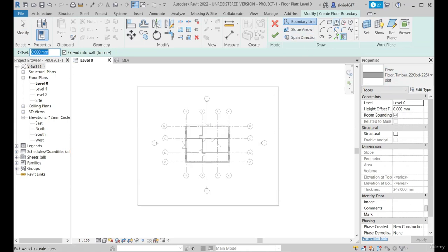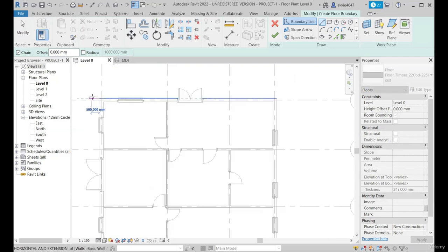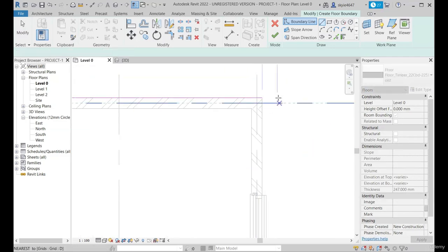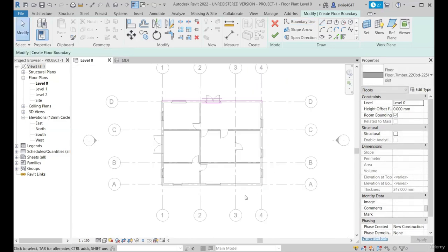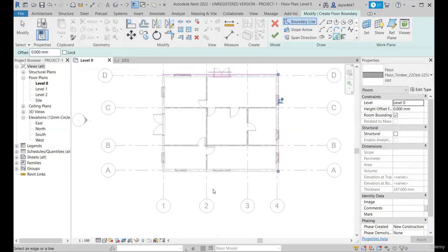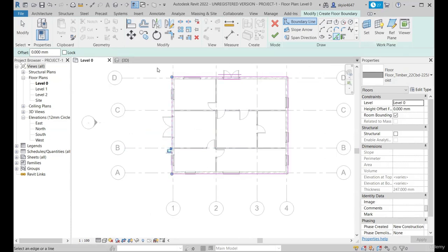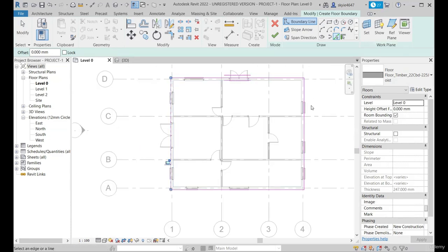In order to draw the floor, we have a few options, as were visible in the wall modeling as well. You have the line, so you can proceed with using the line. If you don't want the line, as we have a reference of these walls that are already present, you can use the pick line. You can use the pick line to model the floor.